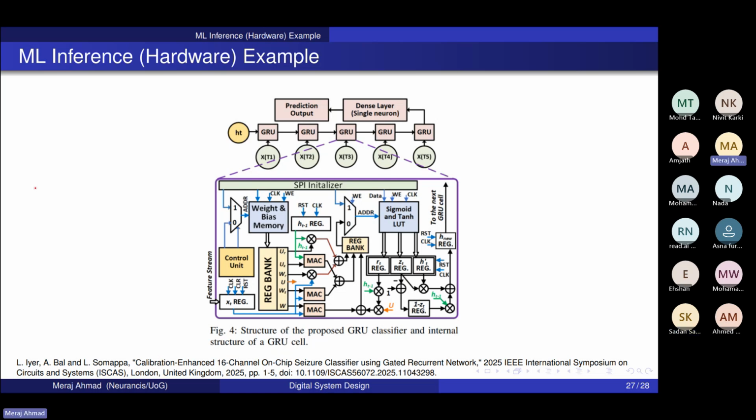Okay. So now this is the data path in which you have a memory, and there are some numbers as weights that you need. Suppose you are implementing an FIR filter. You need a storage where you have h[n], so that when you have some signal x[n] coming in hardware, you use this x[n] and h[n], and there will be mainly a MAC operation, and then you get the output y[n].